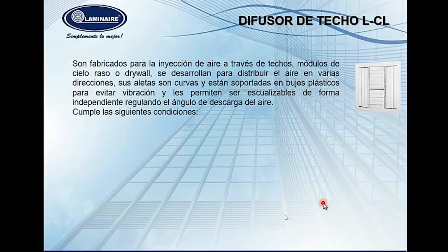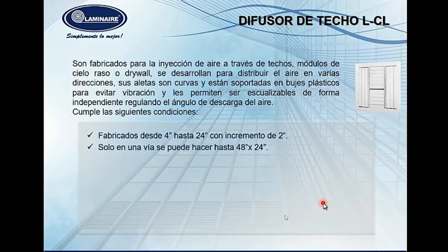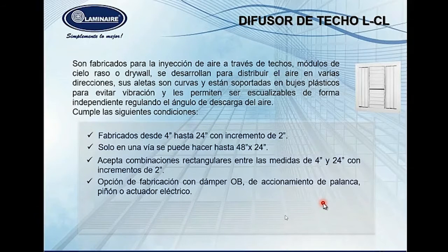They are curved, and these allow to be closed or opened for the distribution. We can change the cone of the distribution of the air, which could be done for specific areas, and this makes the diffuser useful in some heights over 5 meters.